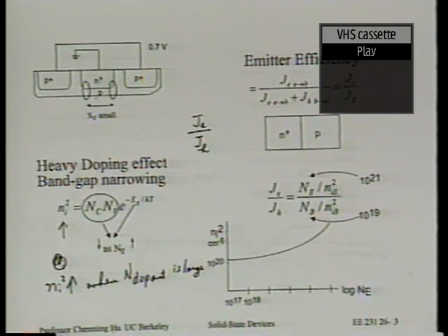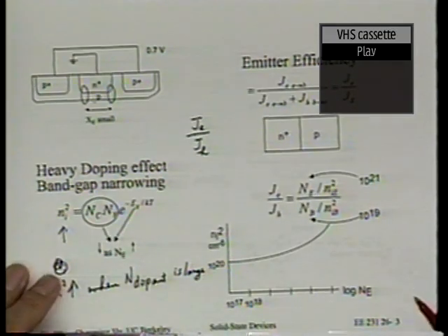We want good current gain. We also want high cutoff frequency. And in fact, cutoff frequency probably is even more important than gain, but both are important. All right? So by using graded doping, silicon germanium, we manage to solve both problems. All right? Okay, good.